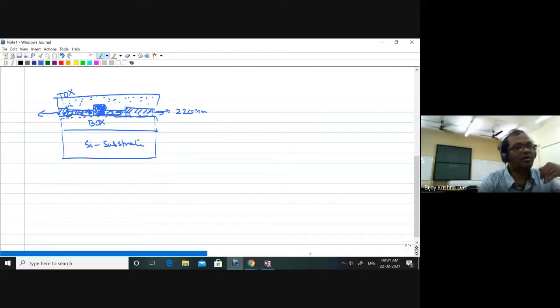Probably you can just recollect whatever I have presented earlier, that we leave some kind of slab region here so that you can dope p-type and n-type if it is silicon, so that you can create also pin type diode structure, and that type of structure is normally used to design modulator. Okay, so whenever you don't need that type of modulator application, only passive waveguide structure, or maybe thermo-optically tunable things, then you can use it just without this slab region.